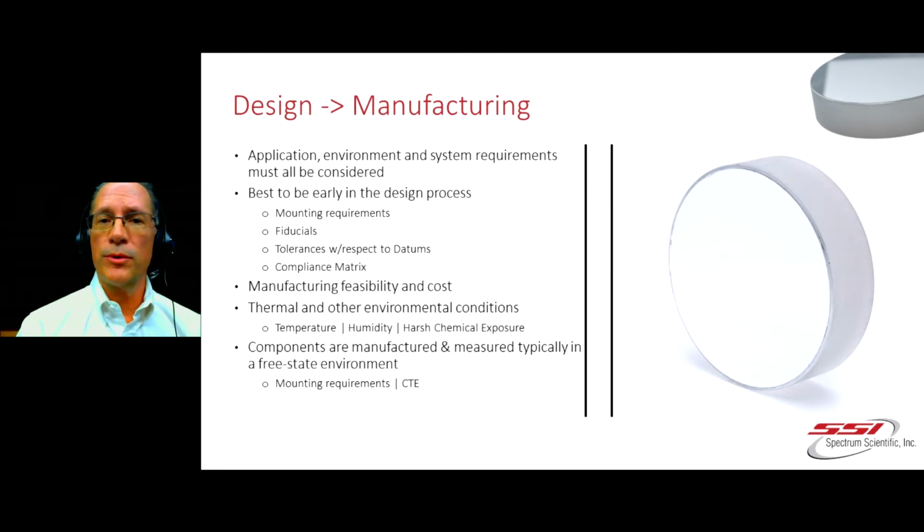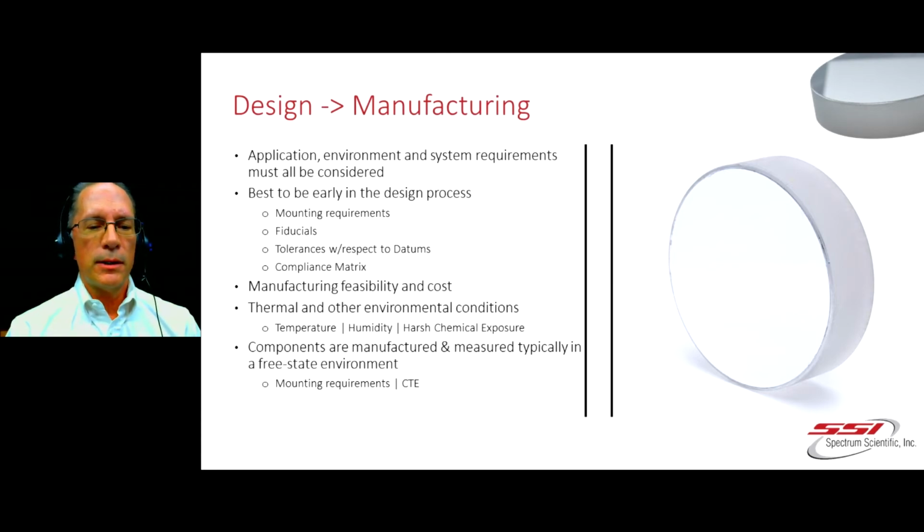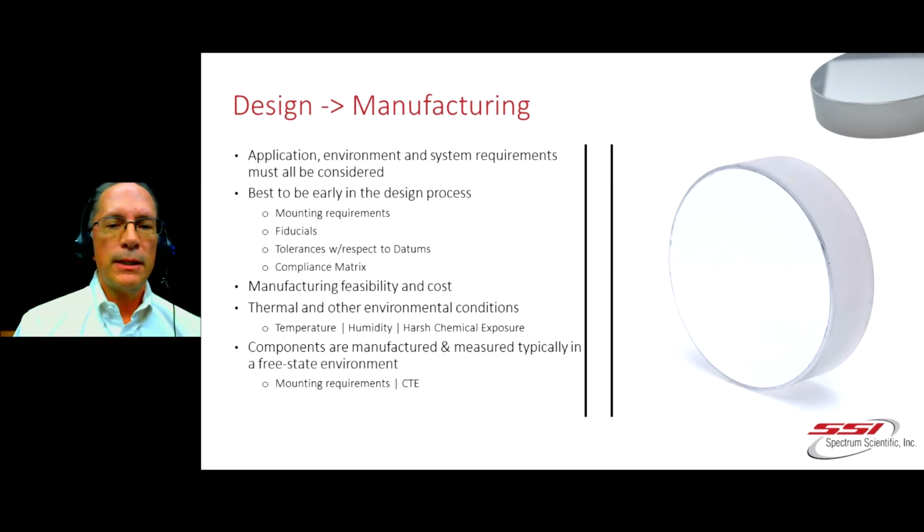I'm sure you have even more things, but mounting is important. That's a huge topic. You can't believe how many times we've delivered a 10th wave optic, and just the mount distorts it. It's amazing how little pressure it takes to distort a 10th or even quarter wave optic. So we encourage talking to the manufacturer, that'd be us, early in your process. Get us involved, ask us questions, and make sure it's a good fit.